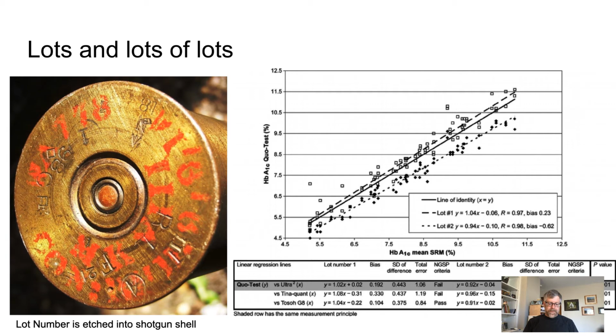And it's just because workers are in a different state of mind on a Wednesday than they are on a Friday. So they do things differently, they behave differently. And so lot numbers are actually very important. If you want these things to have very, very consistent testing and be the same from thing to thing to thing, test to test to test, then you buy the same lot number, you buy the same resistors, you buy the same capacitors, and you just stockpile them and then you use them.